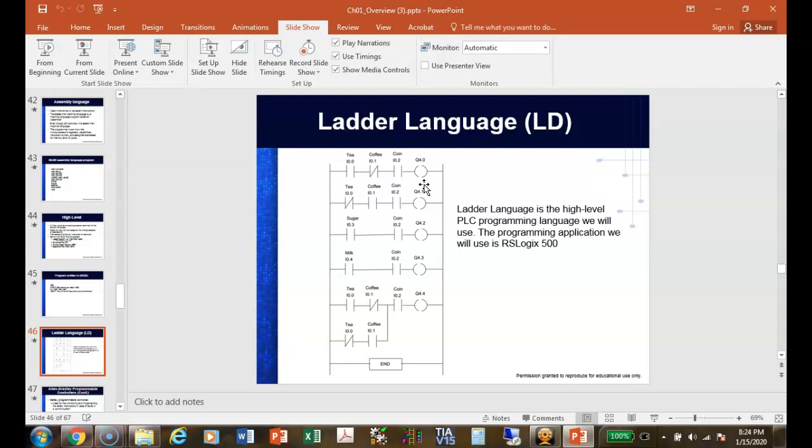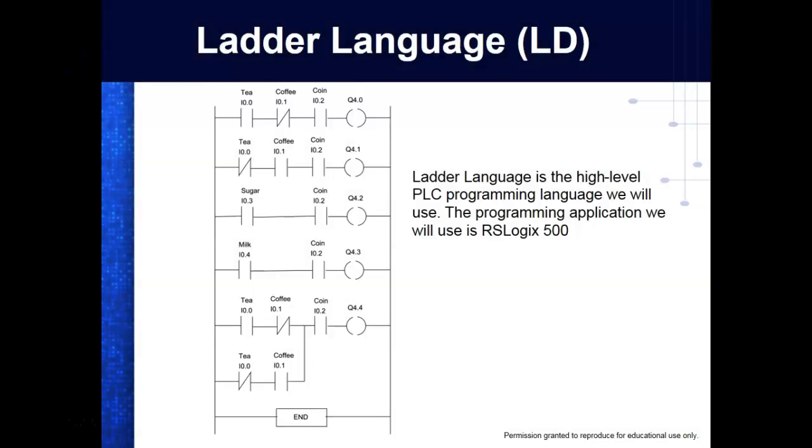And whatever the solenoid controls, that's what this is addressing. This looks like this came from a Siemens PLC because the addressing is a little different. But you notice every instruction, except for these, they've assigned it a what? They've assigned it a name. So once I assign an instruction a name, then I can use the name instead of the address.